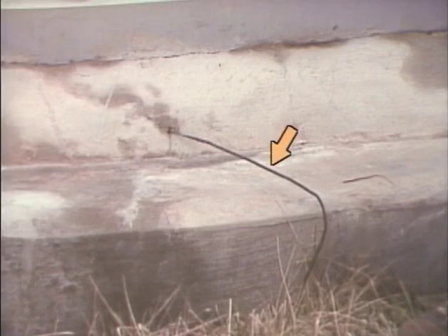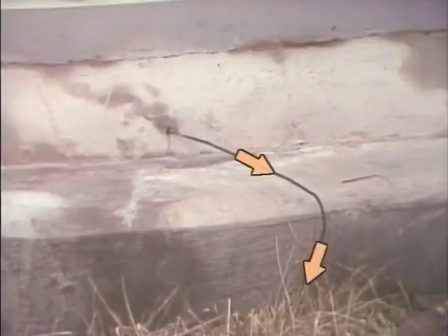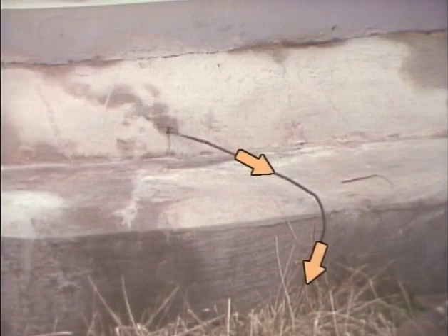They're also connected to a wire in the ground, called a counterpoise wire, that runs along the transmission path. The counterpoise wire also ties the system together and grounds it as well. Since lightning tends to be drawn to the highest point above ground, any lightning that would otherwise strike structures or transmission lines is generally attracted to a static wire. The resultant voltage surge is directed through the static wires to the counterpoise wire and is dissipated to ground, preventing damage to lines and structures.